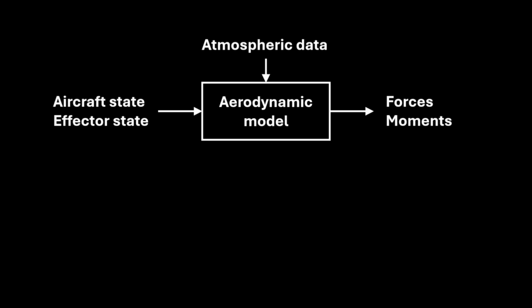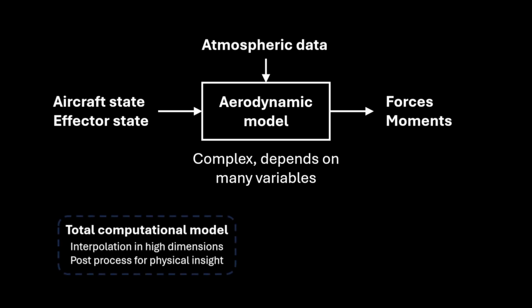The aerodynamic forces and moments are underpinned by complex flow physics that depend on many variables. That said, there are 2 primary approaches to creating aerodynamic models. First, one can use computational tools, such as computational fluid dynamics, to create a set of tables dependent on many input variables. This approach directly determines the model pointwise, essentially resulting in big tables that are interpolated in simulation. One issue with this approach is the cost of using high-dimensional interpolators. It can slow the simulation down.